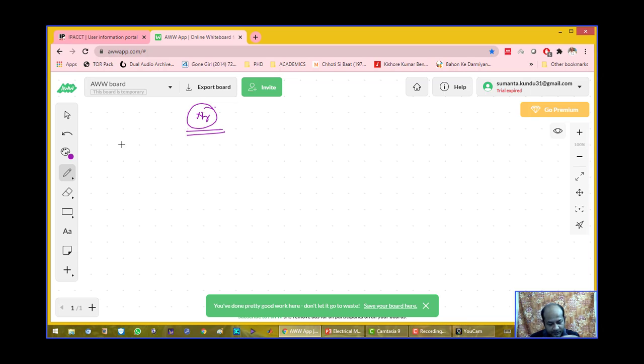But the speed of both fields is the same. They rotate at synchronous speed ns, the stator field. Once the rotor achieves the speed nr, we cut the auxiliary winding from the circuit, and only the main winding remains under running condition. There is no auxiliary winding once it starts rotating in a single direction by some auxiliary means.